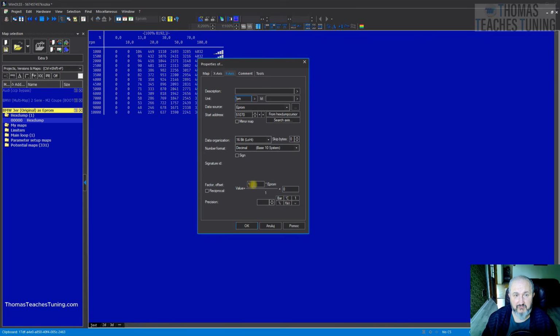In older controllers, so it was EDC16 or EDC15, just in museum cars, there is no need for conversion because it's one-to-one. However, in some other controllers, different conversions may be required. For example, you might need to multiply by 0.25 in Delphi. Sometimes in other systems like Siemens, the conversion is still one-to-one.